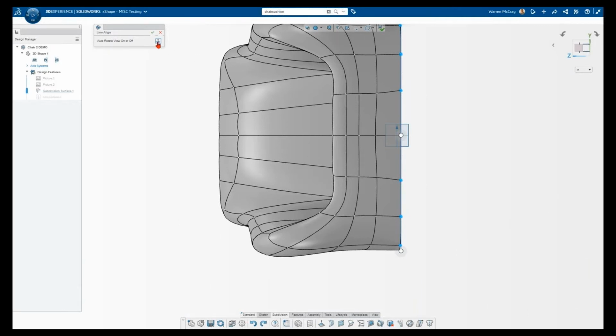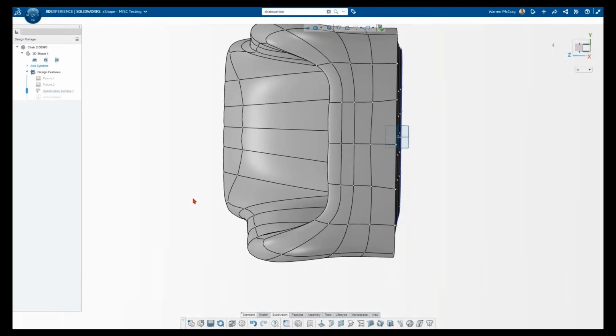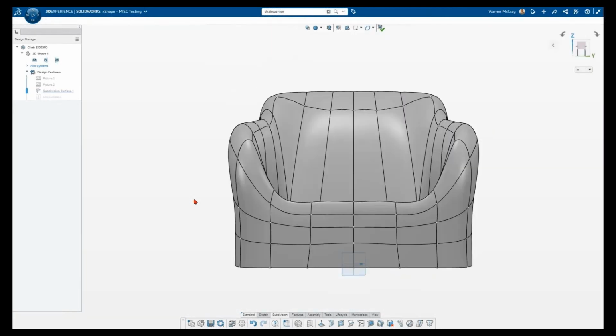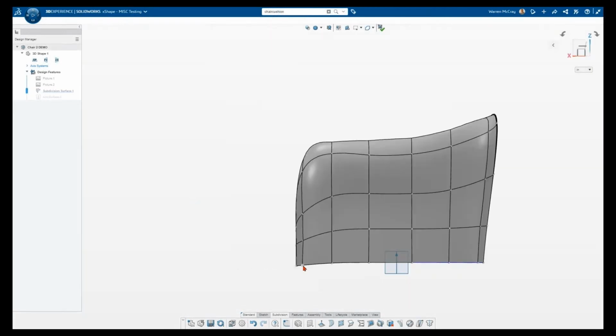Now it's straight, see? Well, that's the front edge there. What about the side? Let's take a look at that. And I'm gonna go ahead and control select all these points. Now the front right there is kind of dipping a little bit, so let me pick that one. There we go. And I'll get all of them on the side and the back too. Get that one too, just those points there, and align them. Right there in the context menu, I click on it, there it is. It lines them up. It's a real fine adjustment.